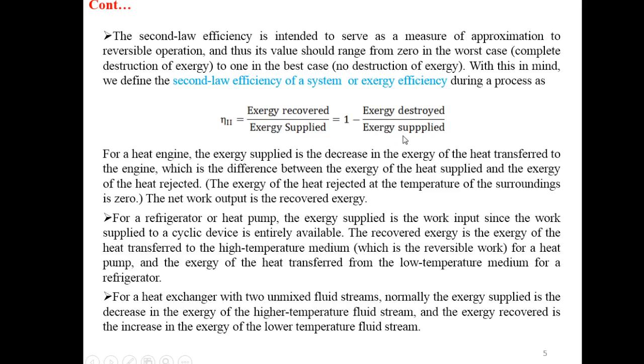For a heat engine, the exergy supplied is the decrease in the exergy of the heat transferred to the engine, which is the difference between the exergy of the heat supplied and the exergy of the heat rejected. The exergy of the heat rejected at the temperature of the surroundings is 0. The net work output is the recovered exergy.